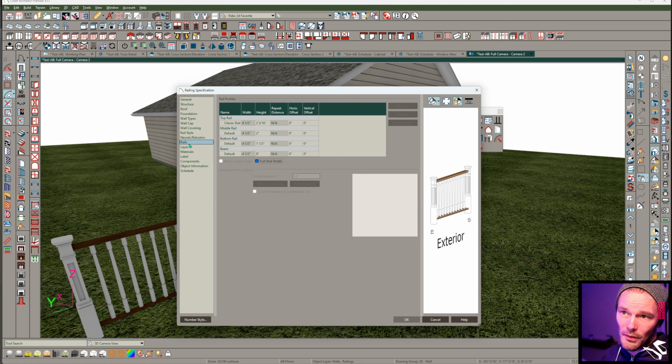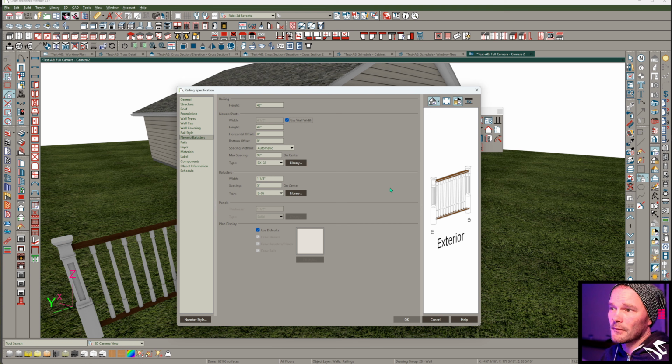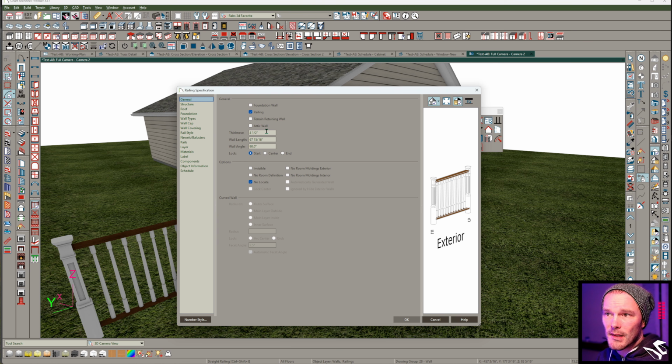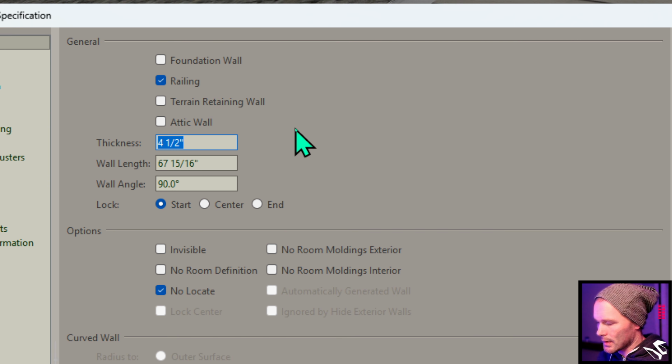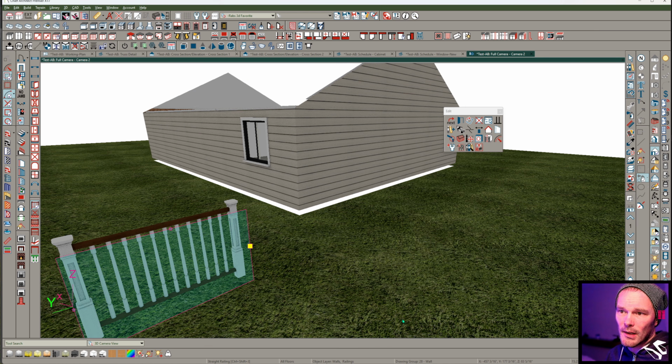But maybe you don't want that. That's one approach. The other thing that you might want instead is your newel post to be full wall width, right? So I would take whatever helps me keep this dynamic so that as I'm rolling through this, I just get to come in here to thickness and say 12, and it's changing all those elements I need it to change very quickly.